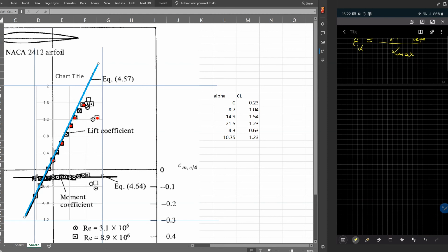So I would like to clarify one more time that this experimental data, for example, what I show you on these graphics, is just 2 parameters. We have the CL graphics as a function of alpha. We have CD from another graphics, which I did not show you, but it exists for this airfoil as a function of alpha. And we have CM as a function of alpha also on this picture. This is what you have.